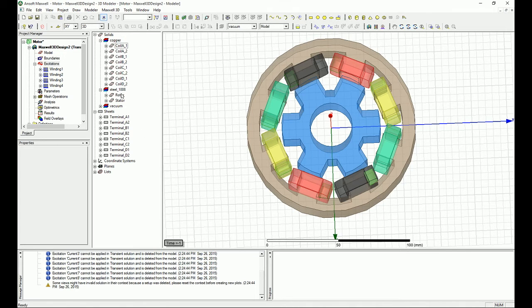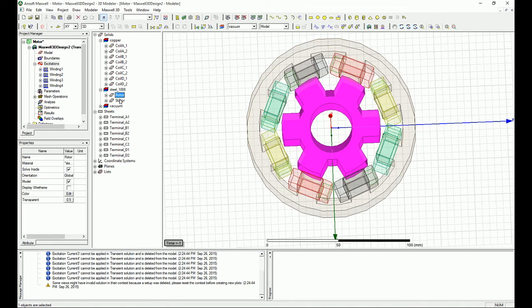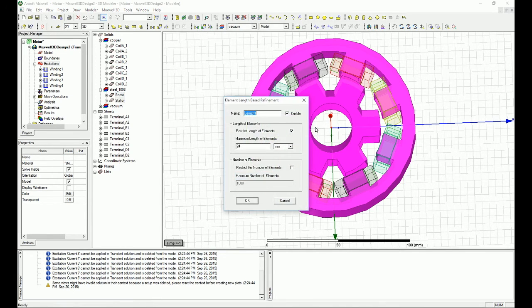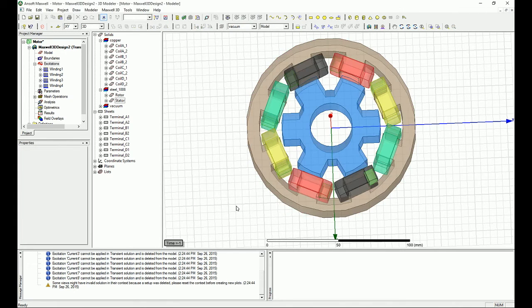Also, let's do the rotor and the stator. I'm selecting both of them and going to the meshing, and same thing here. I'm going to say mesh the rest, meaning the rest of the design, and over there I want to say perhaps 4,000, which is again 2,000 tetrahedra per rotor and stator. Okay, let's press OK for that.